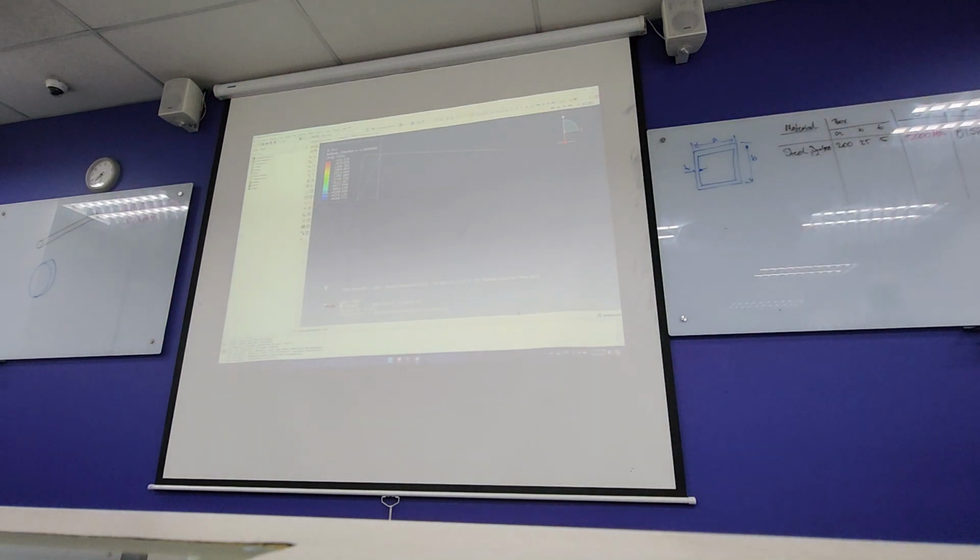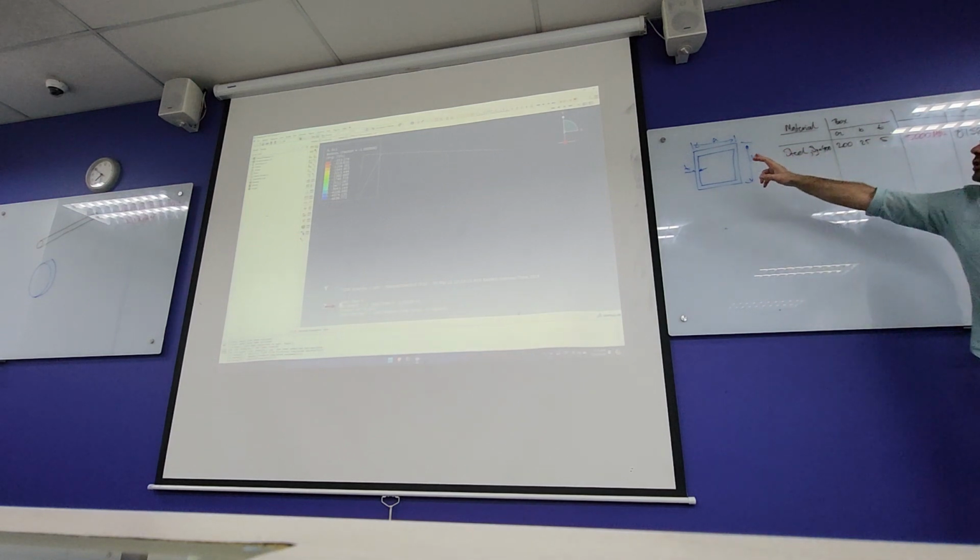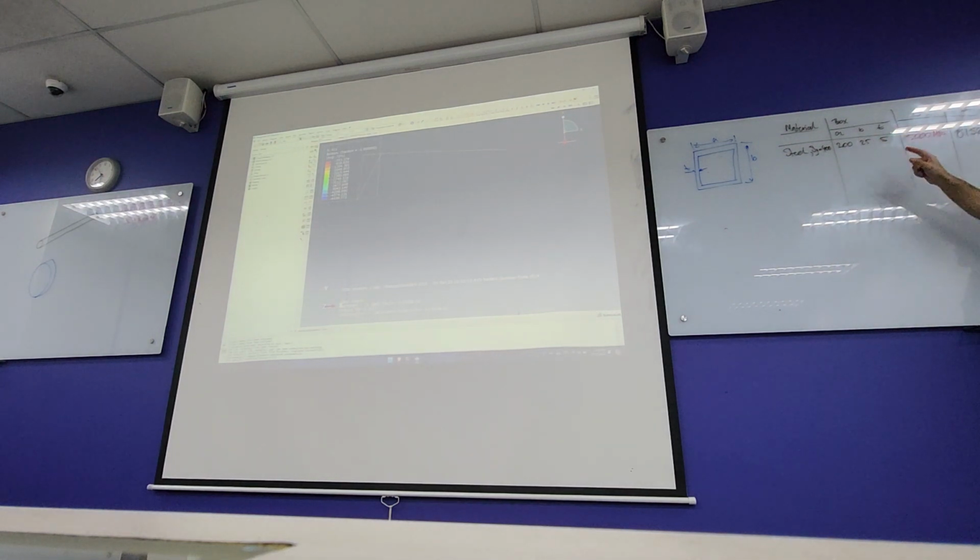I quickly went through some numbers, and that's what I've got. I assume you're going to have a steel of 210 gigapascals Young's modulus, and my box was 200 by 25, and 5 millimeters thick. I did calculations and I got silly numbers. I've got stresses of 5 gigapascals, and a deflection of 8 meters. So not good, yeah? So those numbers don't mean anything. I need to go back, change the values, run it again, and hopefully get it right. Does that make sense?